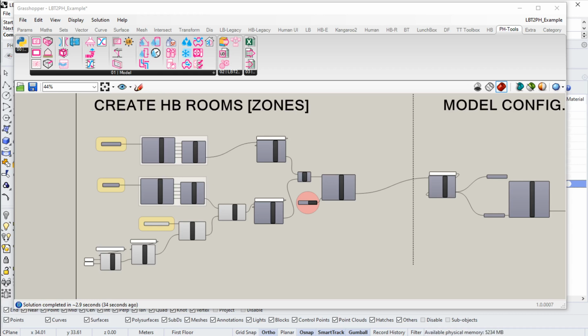So if we want to model our windows more accurately, more in line with the certified Passive House procedures where we're supposed to input things like center of glass U value and frame U value separately, how are we gonna do that here? How can we enter all of that information? And as I showed, using the native Honeybee tools and using the standard EnergyPlus methods, we can't. That's not how EnergyPlus, OpenStudio, or Honeybee work.